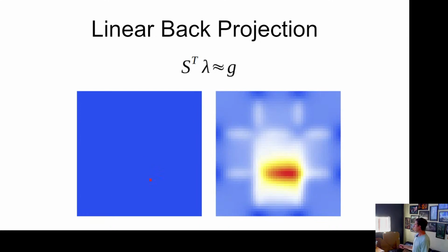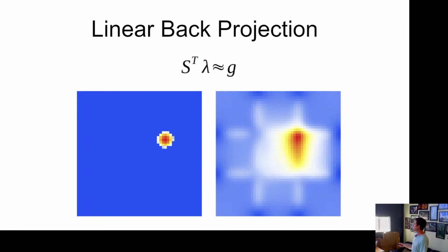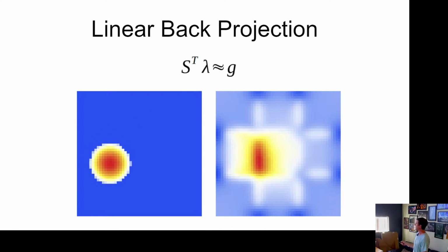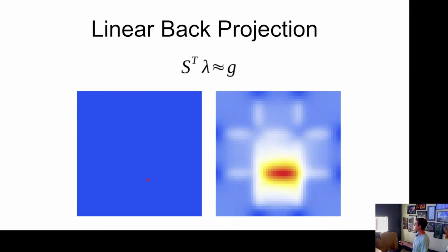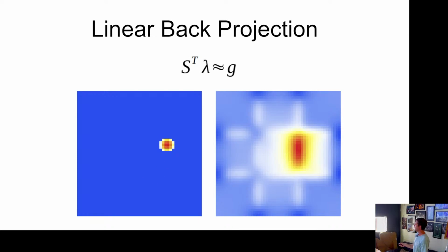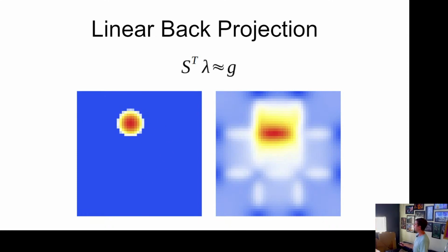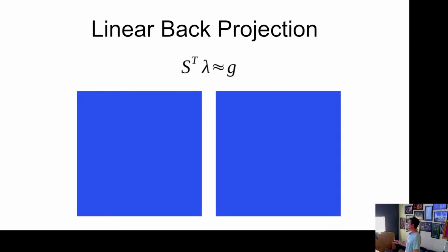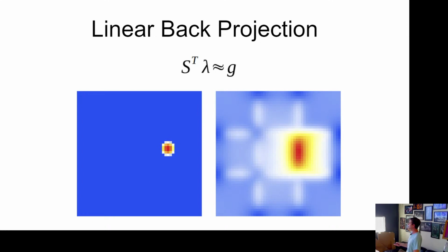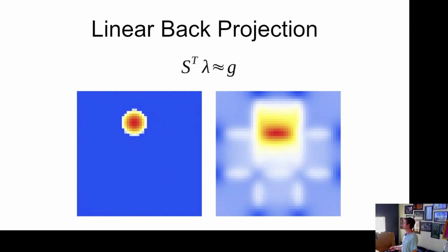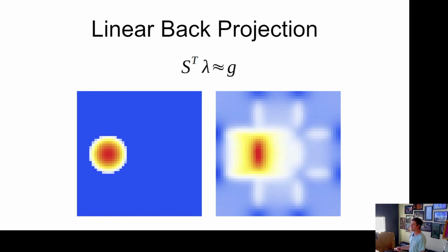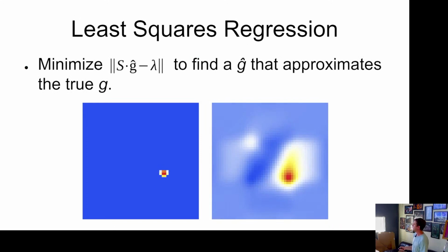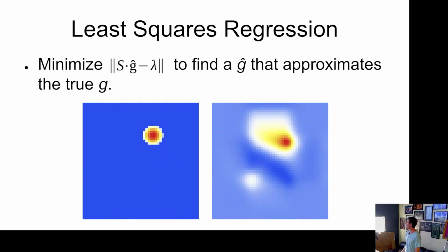As you can see, there are a lot of imaging artifacts here. The size is not accurately captured, and you can see artifacts from the matrix itself showing where there's a higher level of sensitivity between the electrodes. So this would tell you where the corrosion is on the surface, but it doesn't really tell you how much you have, and it could be fooled pretty easily by a lot of different things. So not the best approach. A better approach is what's called least squares regression.